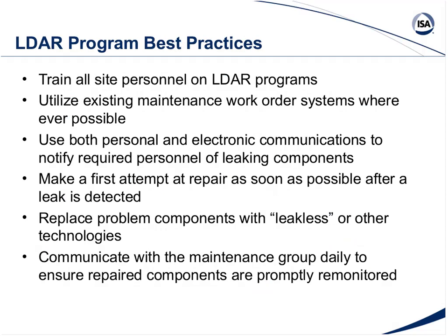So here are some program best practices. You want to make sure people are trained on the LDAR program. A couple of best practices I've seen is that they actually ran slides on leak detection and repair in the break rooms, so that they had those up there, and they had competitions between process units. So there's some other things to look at. You want to make sure you use your existing maintenance work order systems, your existing systems whenever possible. When you have multiple systems, you have a place for multiple points of error. So if you can utilize the same system, the better off you are, because everybody's familiar with those systems, and you don't have those transfers of responsibility.